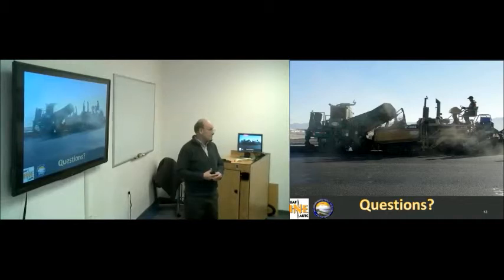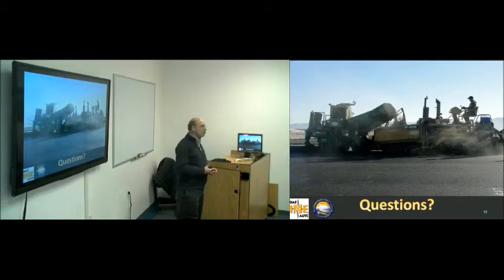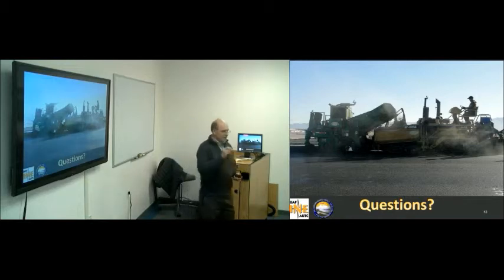The last question I had was, what is Miner's Law? Miner's Law says that every time you load it, it's using some percentage of the load. So the incremental failure, some percentage of the load. A portion of the ESALs that you designed for. So when you add all those up, they equal 100% or less. Once it exceeds 100%, it's failed.